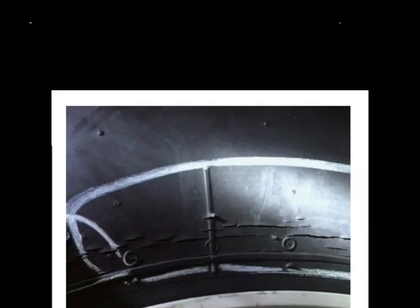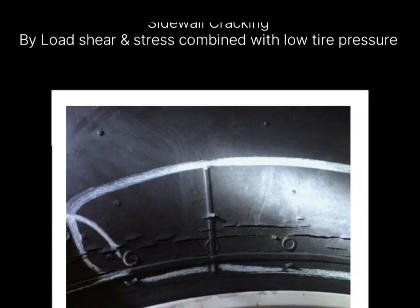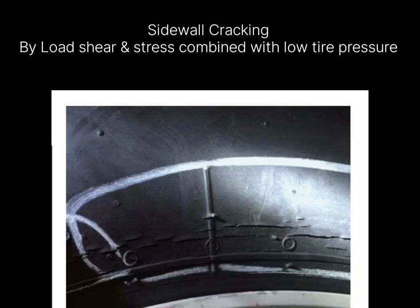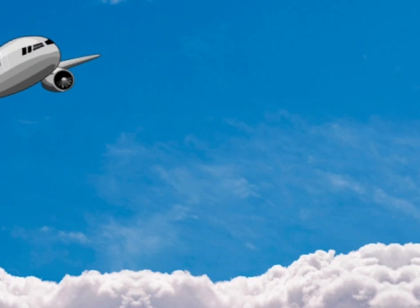Another type is sidewall cracking. Any crack is caused by load shear or stress combined with low tire pressure. Cracking in the area where the tire touches the rim flange can occur due to the mechanical interaction between the rim flange and the lower sidewall of the tire during deflection. If the fabric is exposed, you have to remove the tire from service. So this is all about the different types of tire inspection. This is just for quick reference.